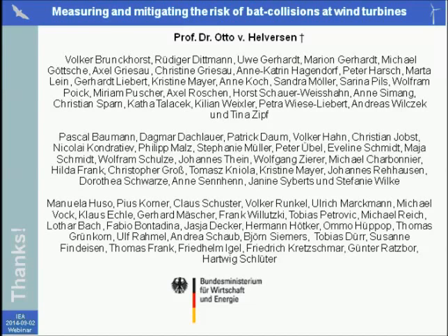We also included night time and month to predict times of collision risk. We also tried precipitation and temperature, but in the end we left them out of the model again because they didn't increase the results substantially, but they would increase the cost of measuring and implementing the algorithms. So that's why we didn't use these variables. We feed this model into the computer running the turbine, and then the computer will shut down the turbine at times of higher collision risk.